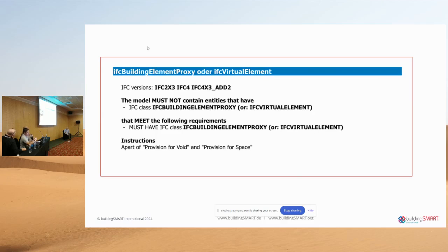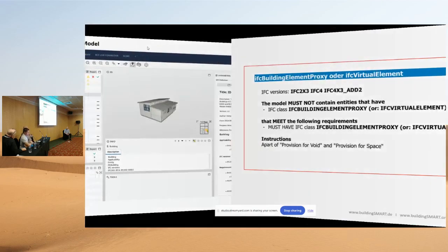I mean, related elements should be properly made by the IFC schema. And of course, in IDS you have a chance to prohibit any element. It's a chance that not many know, to show what is not allowed and what you will find in an IFC building.